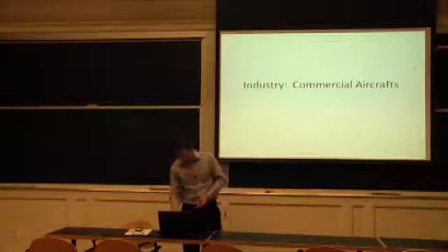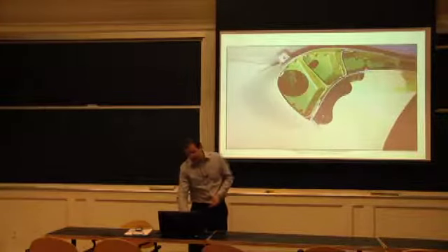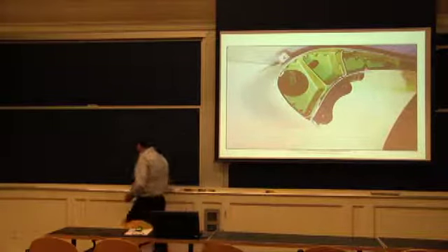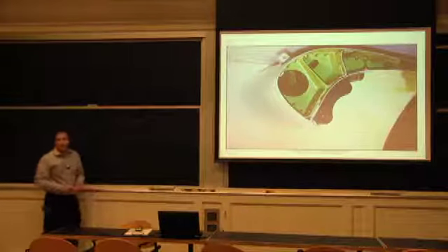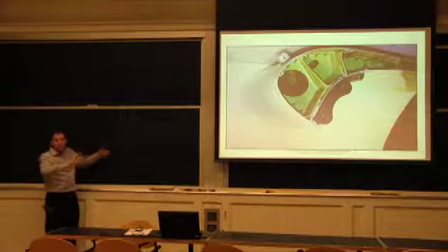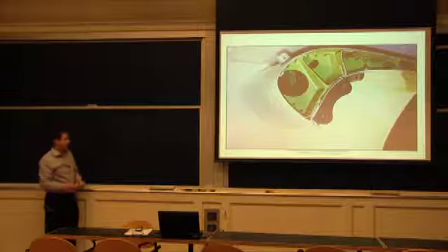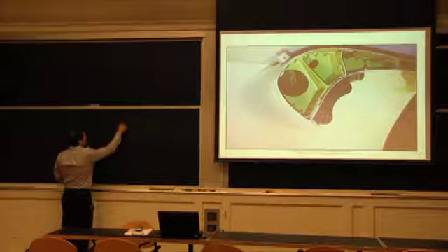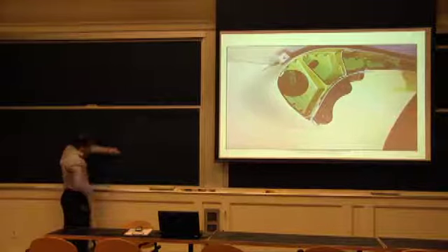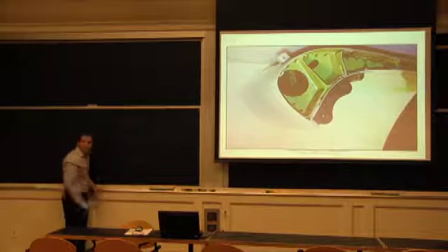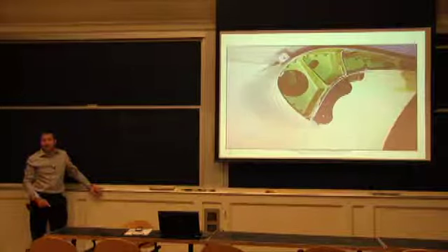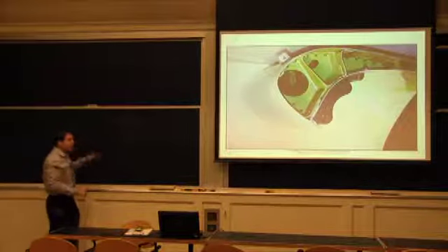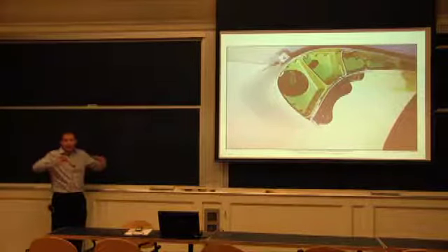So when you go back and say, well, we've got to change the design of this, you can't say, oh, I'm going to go back and do a bending test on all these components and figure out that they are equivalent, because you don't really know all the loading that's going to be applied on this. If you're looking at one of the ribs, it may very well be loaded here and here, or in a diagonal mode, and you'll have some bending, and maybe this is a zone of tension. How do I know? I haven't analyzed it in a full assembly. I've thought about it, I looked at the overall geometry, I have the wind pressure, the uplift, all of that. But what about everything else?